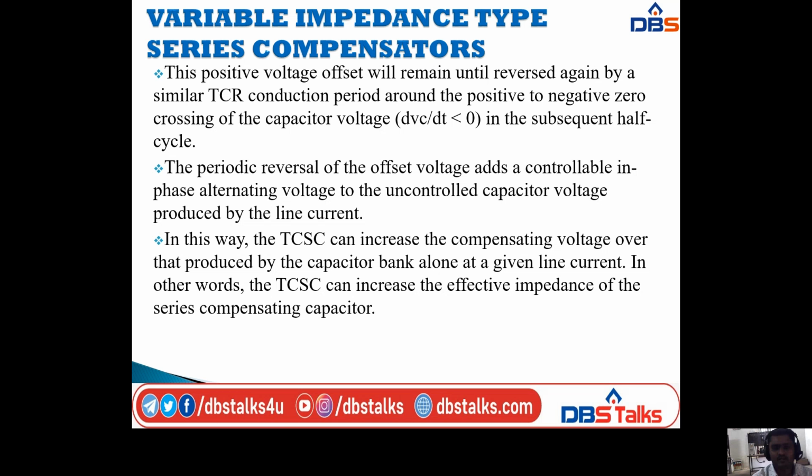This positive voltage offset will remain until reversed again by a similar TCR conduction period around the positive to negative zero crossing of the capacitor voltage, that is dVc by dt is less than 0, in the subsequent half cycle. So the periodic reversal of the offset voltage adds a controllable in-phase alternating voltage to the uncontrolled capacitor voltage produced by the line current.